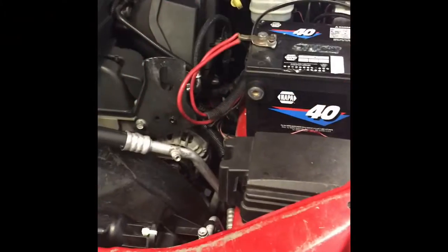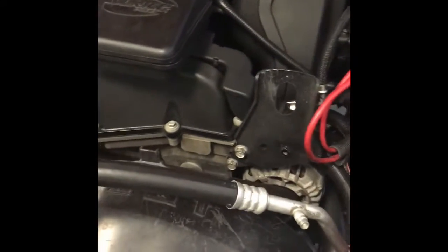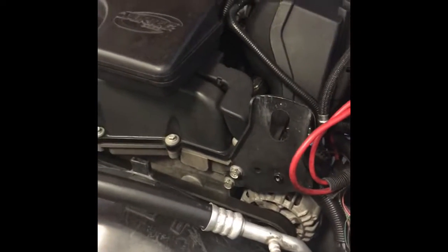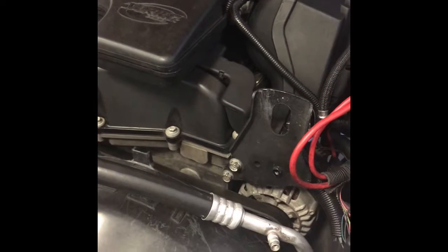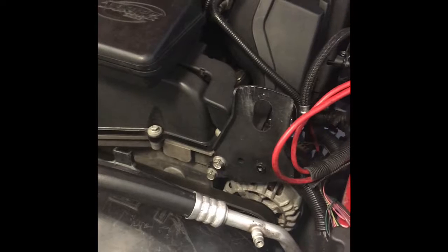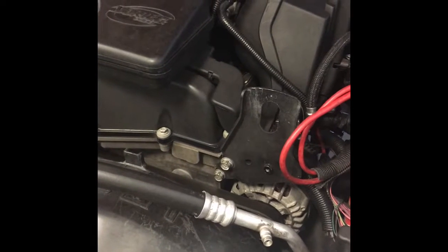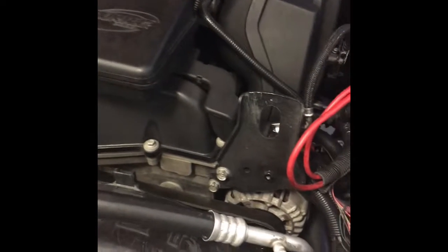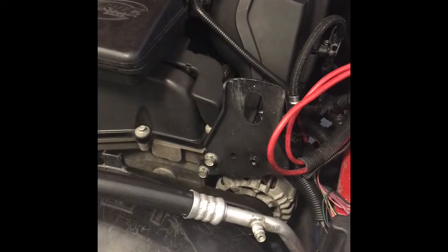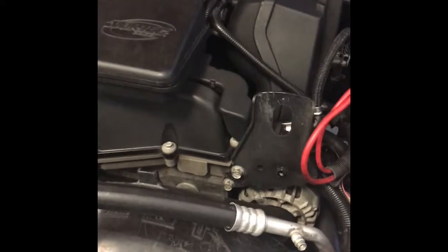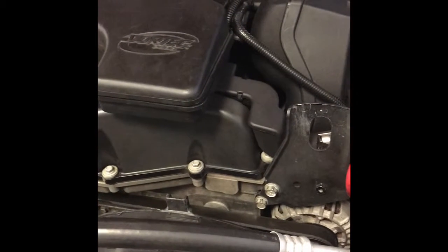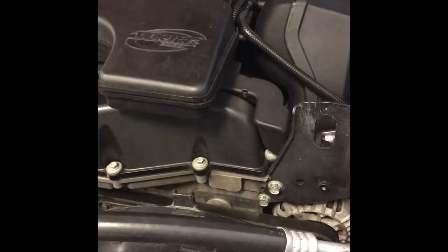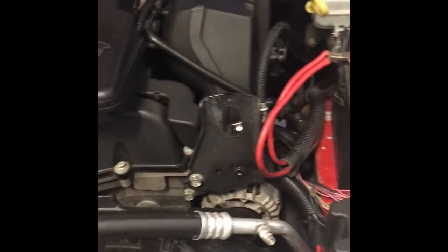Now we're going to cover the air conditioning system. The air conditioning system uses refrigerant and has four major components. The components are the compressor, the condenser, the restrictor, and the evaporator. The compressor changes low pressure refrigerant gas to high pressure gas. The condenser forces the gas to become a liquid. The restrictor lowers the pressure. The evaporator transfers low pressure liquid to low pressure gas. The AC system is also a closed system.